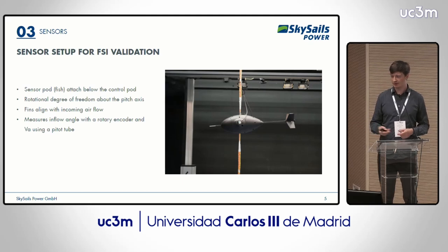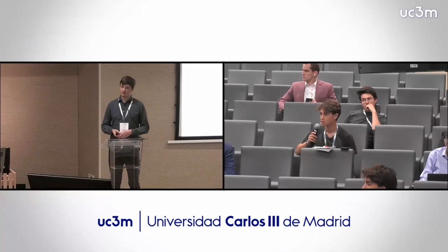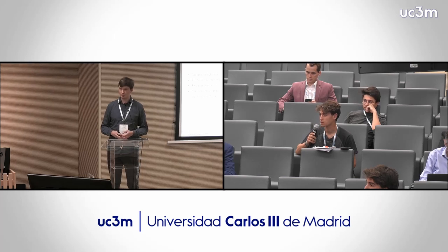And for the CR, you measure the tether force, the apparent wind speed, and also the density of the air. That's how you determine CR. And in which part of the flight do you determine the glide ratio? Is it in dynamic flight or in static flight? It's possible in all stages.